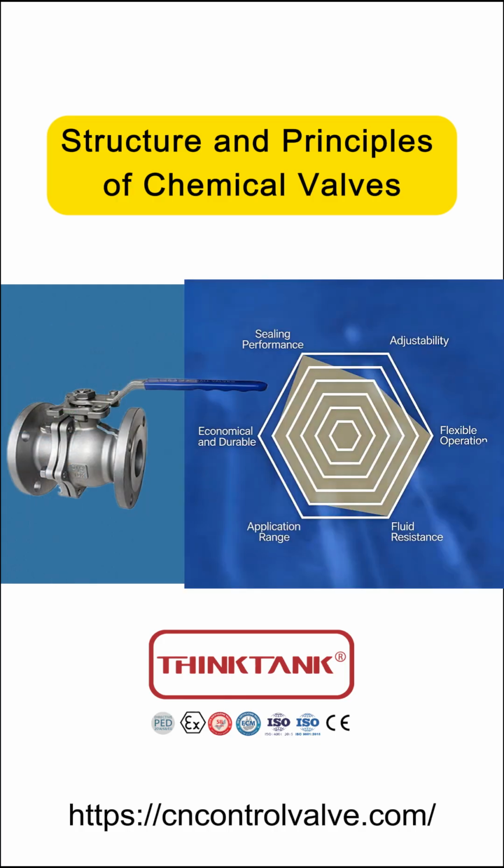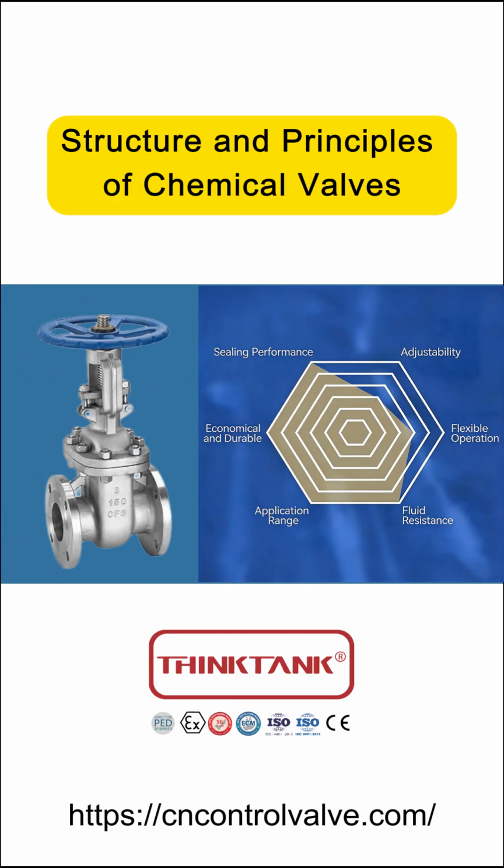Finally, let's summarize. 1. Ball valves are widely applicable. Use floating types for low pressure and trunnion-mounted types for high pressure. Try not to use them for flow regulation, unless they are specialized regulating or V-port ball valves. 2. Gate valves are durable and widely applicable, but their operation time is relatively long. When operating, do not use a cheater bar, as damage to the sealing surface is irreversible. Also, like ball valves, do not use them for flow regulation.